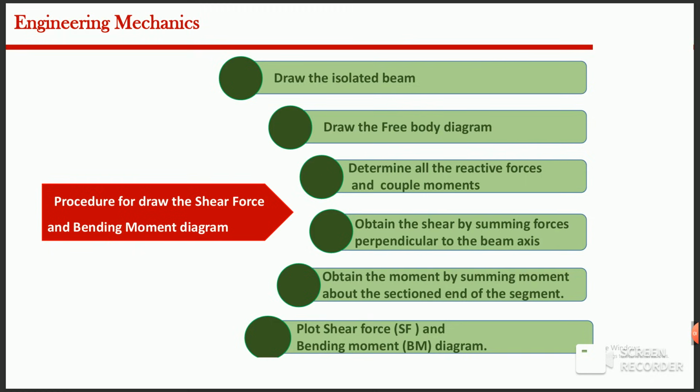In step 4, calculate the shear force at important sections by adding the vertical forces. Then calculate the bending moment at the same sections by taking moments. Finally, step 6, use these calculated values to draw the shear force diagram and the bending moment diagram. If you always follow these 6 steps, solving beam problems becomes much easier and more organized.